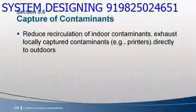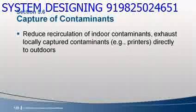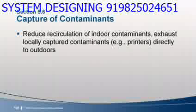Section 5.6 requires that contaminants from non-combustion sources, like printers or copy machines, must be captured locally and exhausted. They can't be allowed to simply mix with return air and recirculate throughout the building.